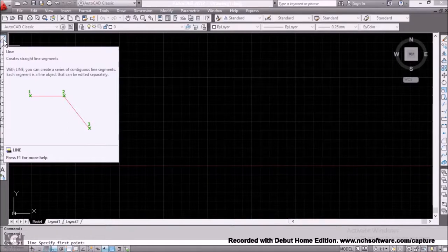There are 5 ways you can use the line tool perfectly in AutoCAD: the absolute coordinate method, the interactive method, the relative rectangular coordinate method, the relative polar coordinate method, and the direct distance entry technique. So I was able to explain the 5 methods of how to use the line tool.